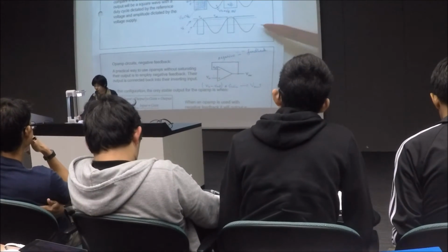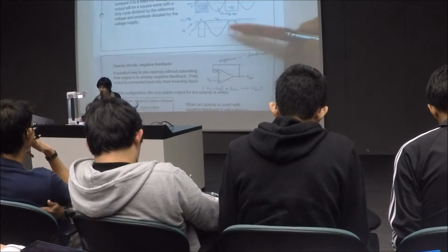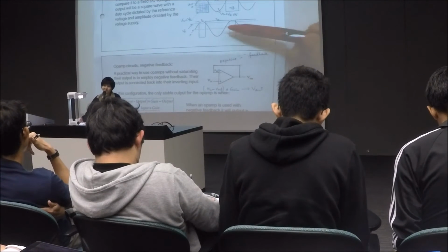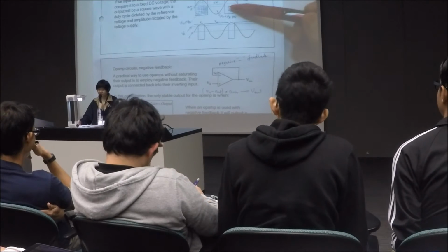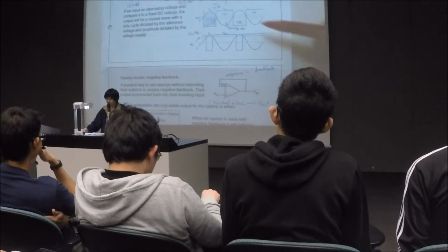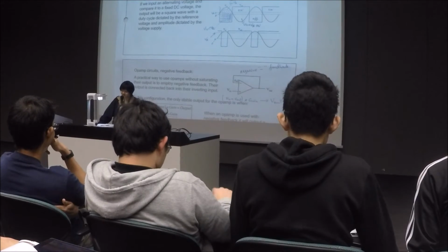So this shows another case where VR is slightly bigger. You can see the duty cycle is actually bigger. And if you further reduce VR, the duty cycle will decrease.